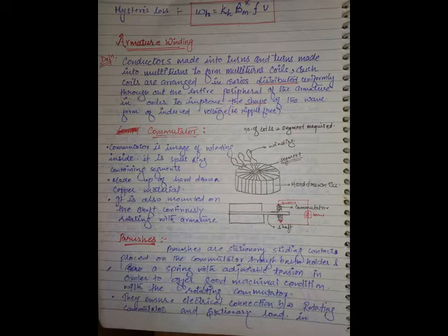After some instant of time, the next coil comes and can we say this is the voltage induced? After some time, the next coil comes and again a voltage is induced. So, as the winding is uniformly distributed, what is the total voltage now? If you add them, the total voltage is like this. You understand?